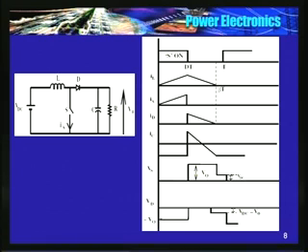At this instant inductor current is equal to the load current, so capacitor current becomes 0. Beyond this point, inductor current decreases, capacitor starts discharging, and when the current has become 0, the entire load current is being supplied by the capacitor.